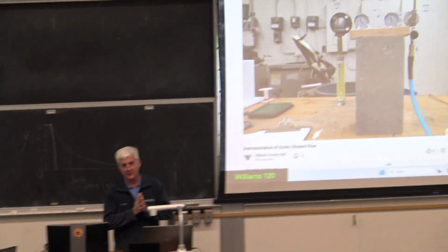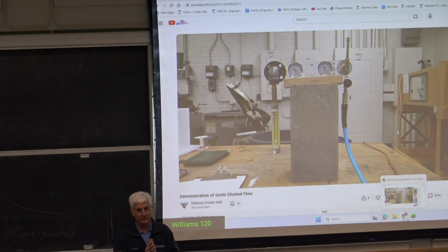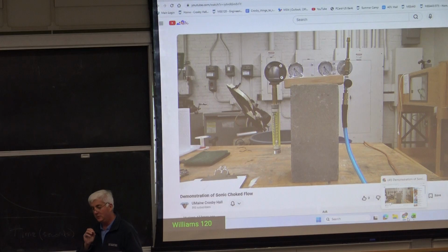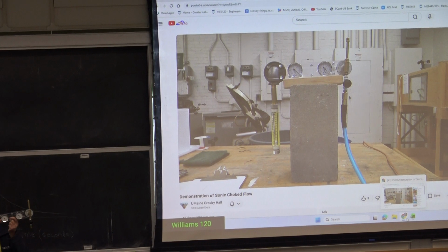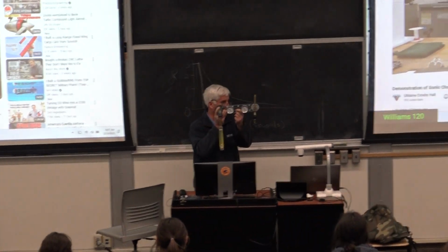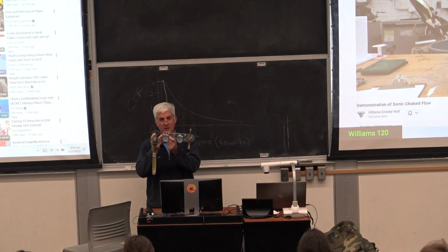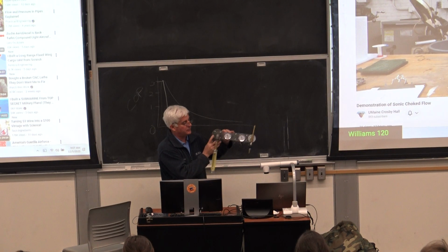Okay, so back when I was talking about sonic flow, one of the things I went over was critical pressure. When you hit Mach 1 at the narrowest point of a flow channel, you become sonically choked. And regardless of how much you lower the downstream pressure, you do not flow any more material. Okay, so we're going to demonstrate that.